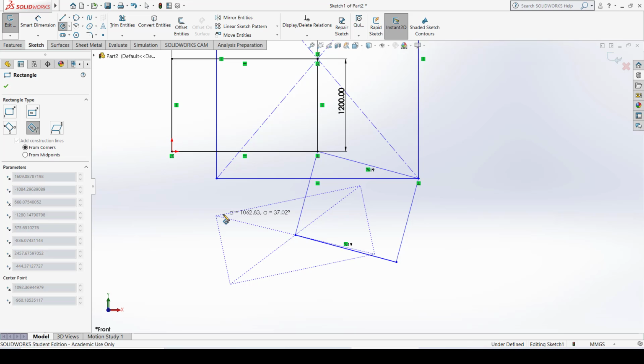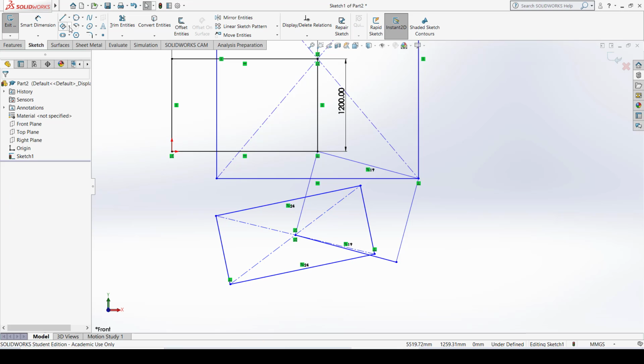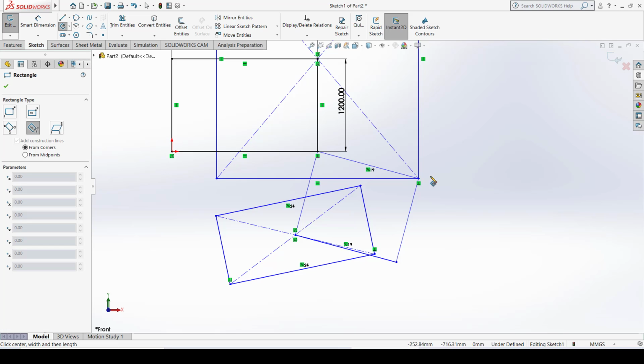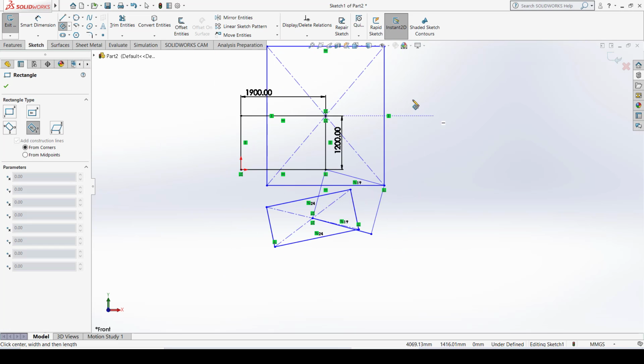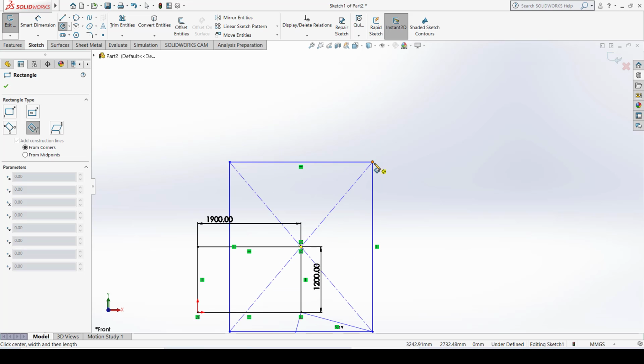This is how you can create a rectangle. Again, I can show you again, the 3-point center rectangle. What happens? If this is the first point, this becomes the center of the rectangle. You can see here on the icon in the left side in the property manager, 1, 2, 3 is written on the points. So 1 means the center of the rectangle, 2 means the midpoint of that line which expands, and 3 is the point where the expansion of this rectangle ends.